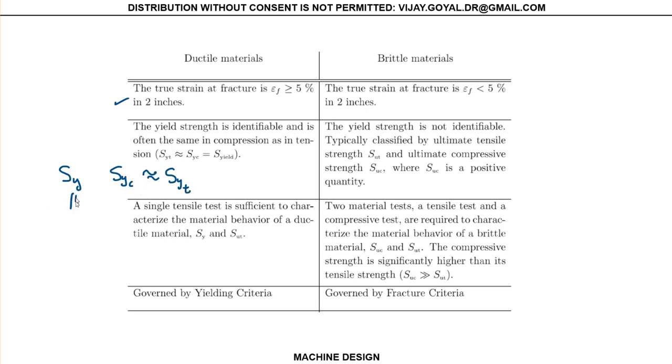If that was not the case for a ductile material, you could say that the sigma yield I will use is just the average of both of them. However, when you go to industry, methods vary, and the industry actually treats the compressive value separate and the tension value separate. I will leave it to each one of the companies to explain how they manage that.